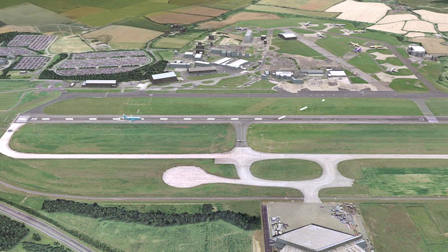The speed VMU is defined as the minimum unstick speed. VMU is the slowest calibrated airspeed at which the aeroplane can safely lift off the ground and continue the takeoff. However, despite VMU being the lowest speed the aeroplane can safely lift off the runway, in actual operating conditions, the aeroplane does not lift off at this speed. The aeroplane is flown so that it actually lifts off at a slightly faster speed.